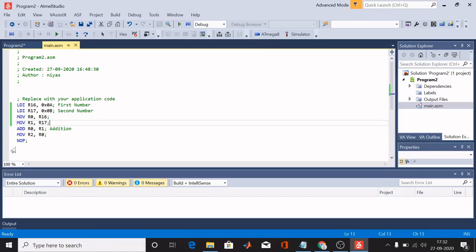If the program execution is finished when we are running the program, we won't be able to view the values of the registers, the memory or the IO ports. In order to avoid that problem, you have to put a breakpoint. You click on the leftmost side of the program. There is a red circle coming that corresponds to a breakpoint.